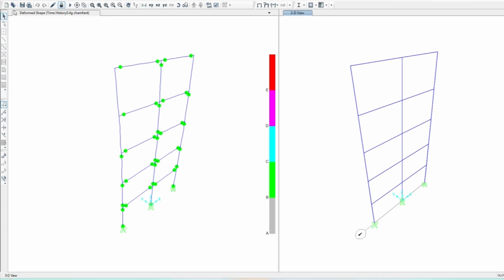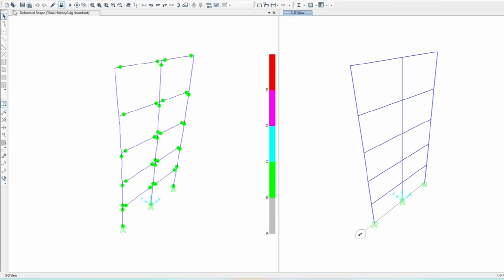I have earlier prepared the model and the design check is done for it. The reinforcement is 10 bars of 16 mm diameter, and the confinement reinforcement is 8 mm at 0.15 meter center to center. The beam size is taken as 0.3 by 0.45 meters. Slab depth considered is 0.15 meter. The loads are dead load and live load of 5 kN per meter square. So as told earlier, for the analysis I am considering the middle frame.